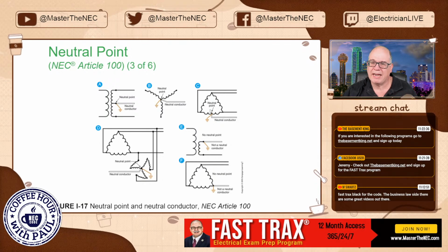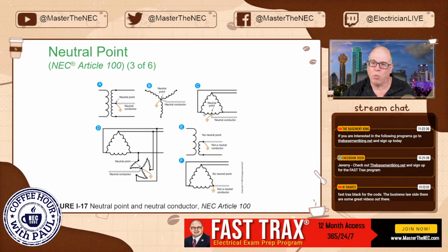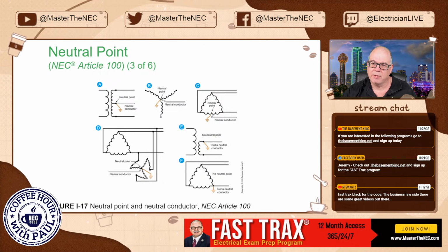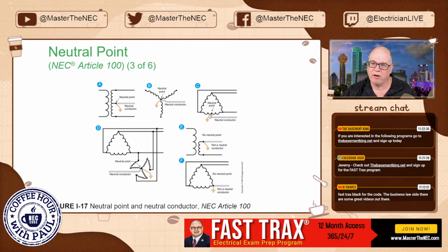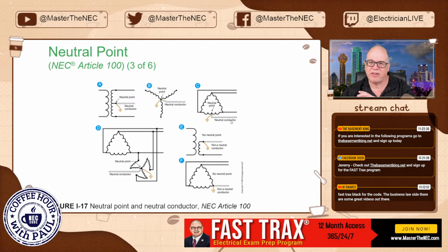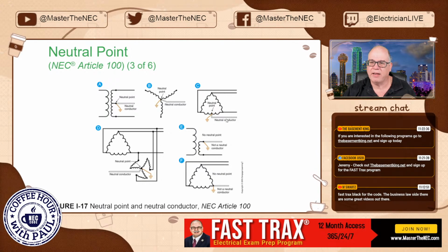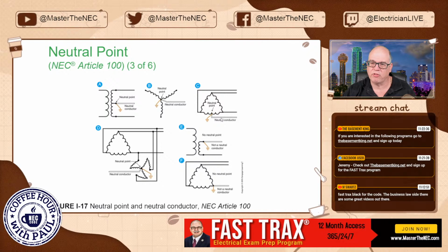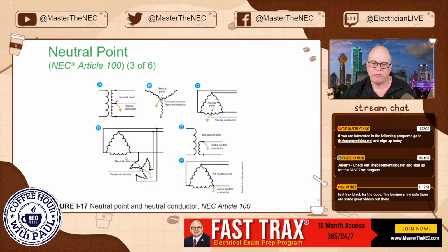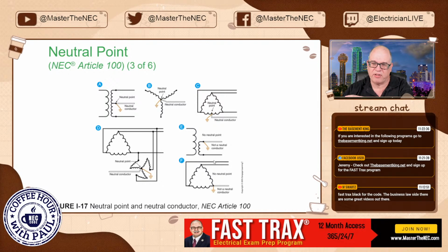Okay, so right here, we have a delta system, but we have one of the windings that's center tapped. So this point right here, when used to derive this set of systems, would be the neutral point. Okay, so this is a neutral conductor. All right, so you have all different types of setups.